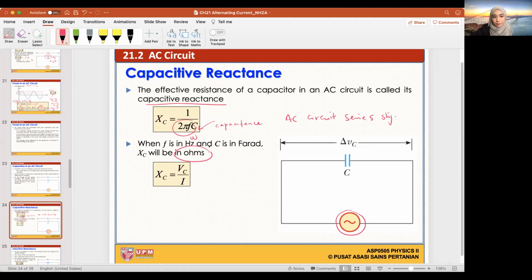In DC circuit, capacitors have the unit of farad, but in AC circuit, this guy has an ohms. It's weird, but it's a good weird because now we can combine. Okay, so it's in ohms, and the equation is Xc equals to 1 over omega C, where C is the value of the capacitor, or 1 over 2 pi f C. So that's your first one.